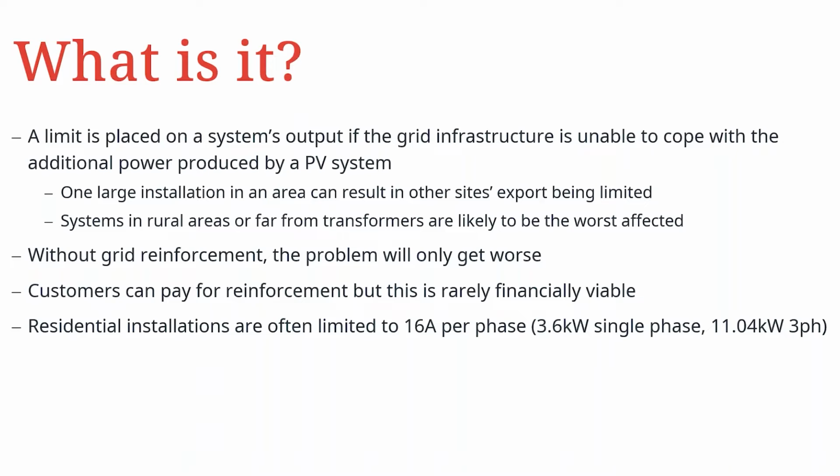And of course, now with the new fast track export limitation requirements with the SIG scheme, we can install larger PV installations on residential properties and normally only have a 10-day turnaround. This means that we can install maybe a 10 kilowatt inverter or an 8 kilowatt inverter and export limit that to 16 amps per phase, which is 3.6 kilowatts. And this is becoming quite an interesting option for a lot of installers.